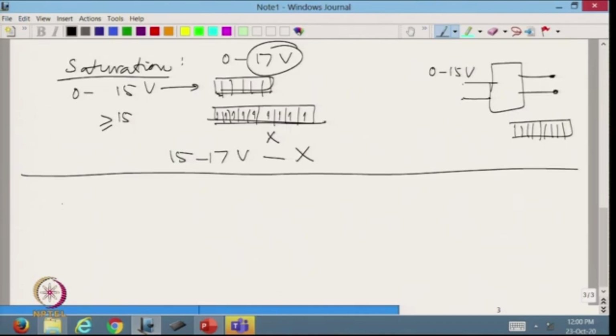Then we have a case where there are certain devices which will give out a signal in a plus minus range. So, this signal could be plus minus say 5 volts. Now, A to D converter does not like minus volt signals. So, what we do is we do a pre-processing and map minus 5 volts to plus 5 volts to 0 and plus 10 volts.